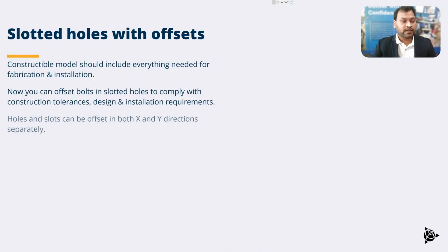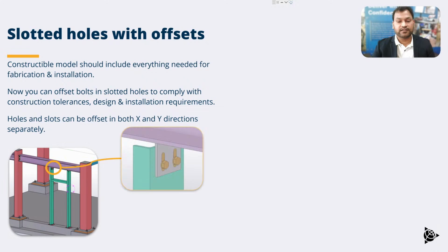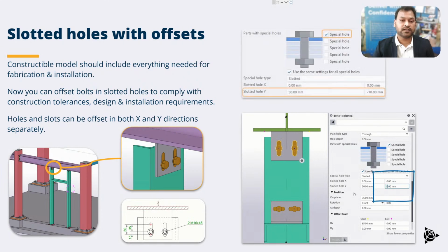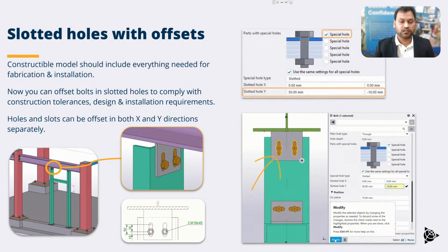Next, coming to the slotted holes with offsets. Most of the time in fabrication, installation, or design, wherever thermal expansion or seismic load vibrations are a concern, we need to give the holes at an offset distance on the slot.